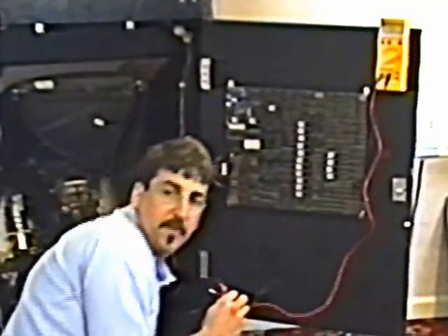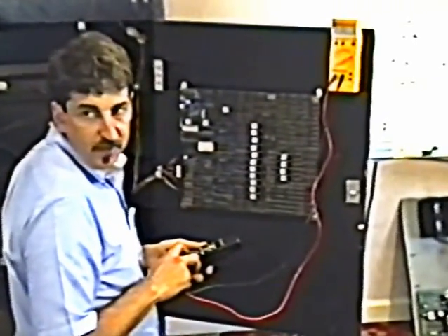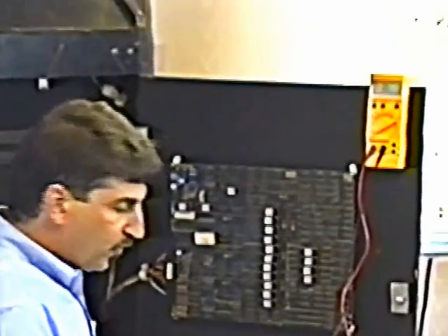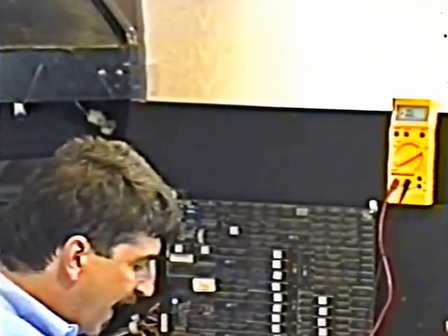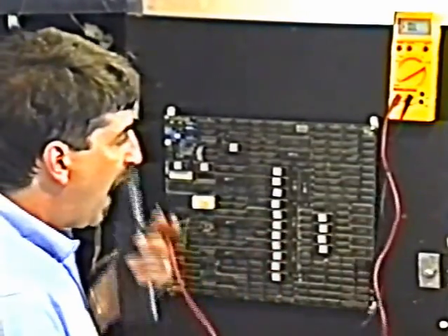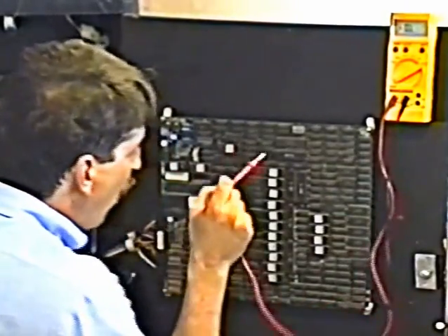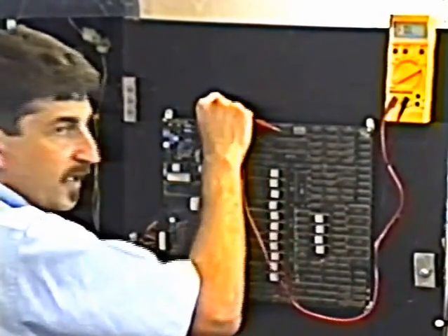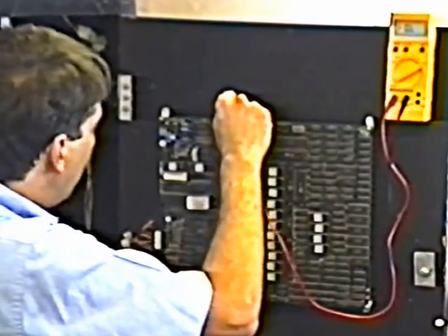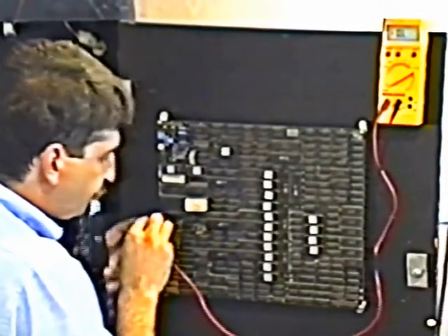Now here's what's weird about this particular test. In this particular test, you are going to ground the red meter lead. This is what's weird about this. You're going to ground the red meter lead. So you need to find a ground somewhere. Well, we know that that corner pin of the integrated circuit is ground, right? And if I ground it on one IC, I'm grounded everywhere. Or I could put it over here on this ground. It doesn't matter. Just get it on ground somehow.